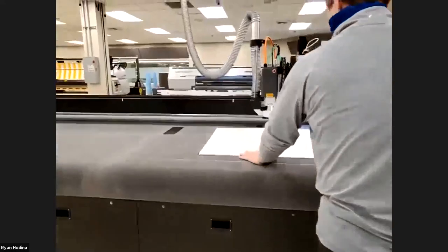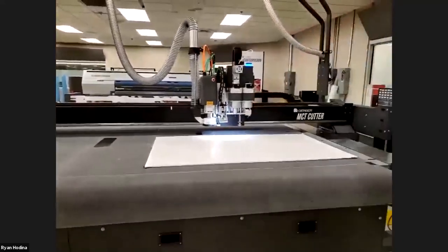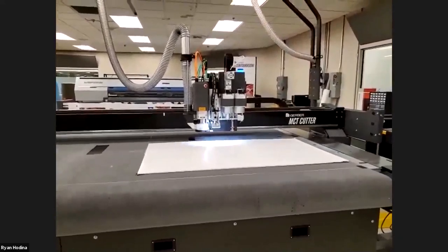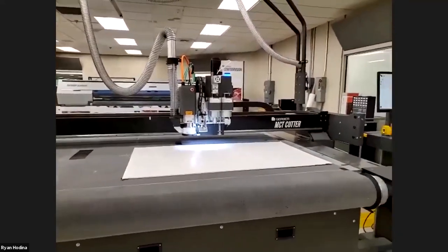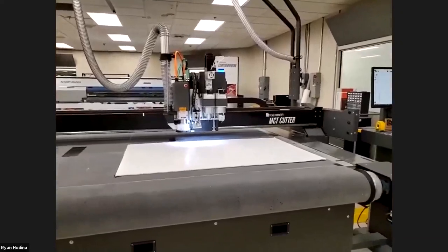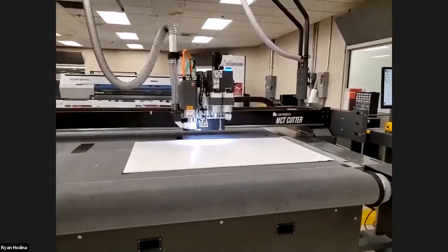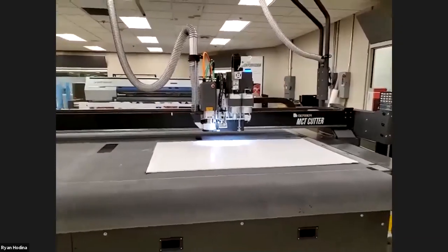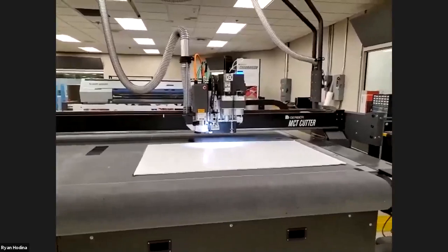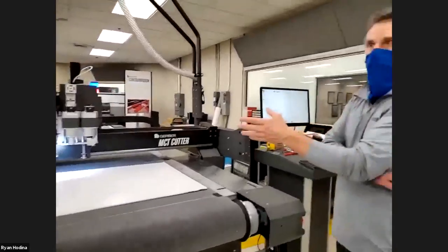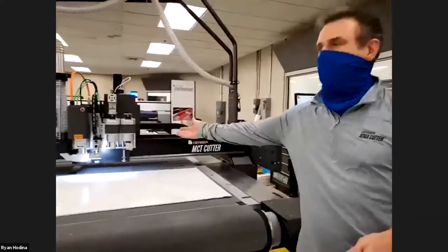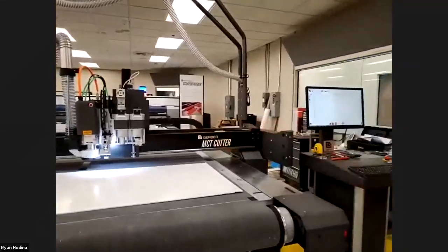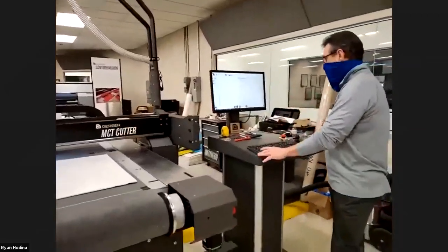So we're going to start with knife cutting. Right now we're going to show basically a display application. We're going to use the oscillating knife to cut the perimeter, and then we're going to use the bevel tool to cut a 45-degree angle so you can fold material like you would for a POP, POS display. Typically we do a tool touch off right now, but since we've already been using this oscillating blade and the bevel knife, we've already done our tool touch offs on that. So we're just going to come straight over here.